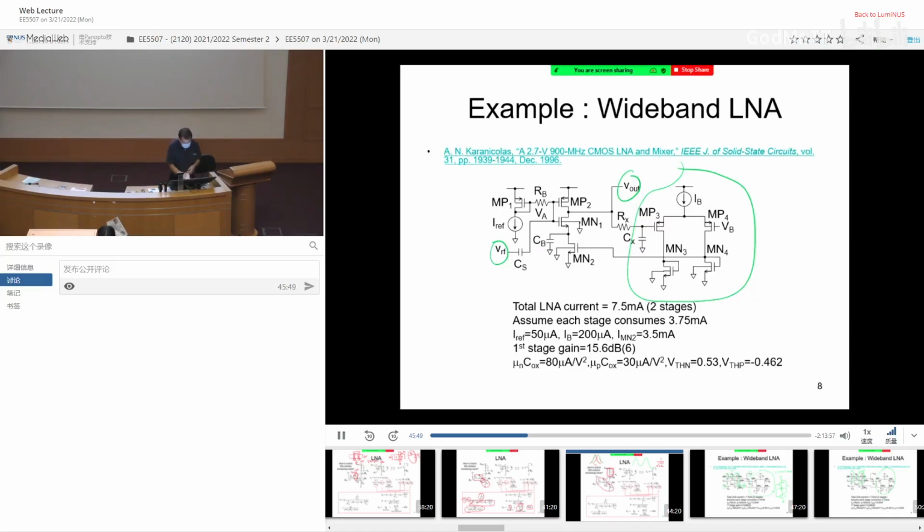Now, this looks like a current source. This looks like some biasing. This is basically just to provide a resistance so that I will not right away get a very low 1/gm equivalent resistance. Now this is the common source amplifier, but this has a particular name. People call it current reuse.